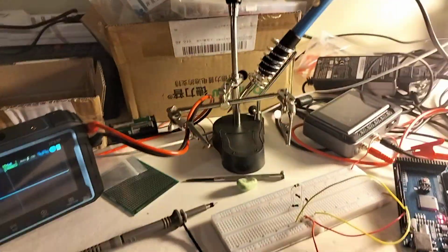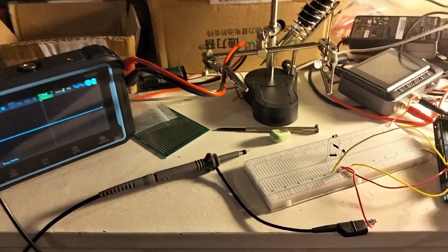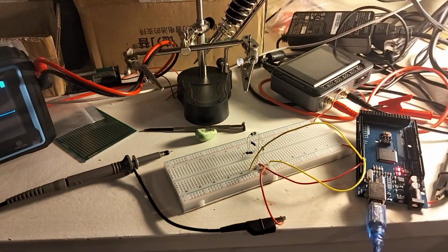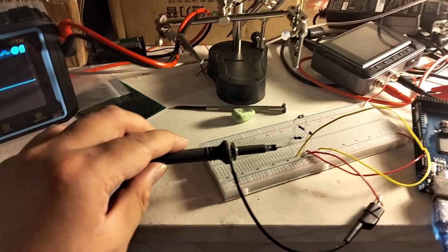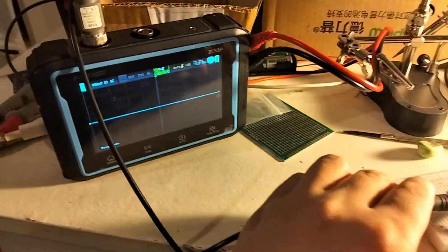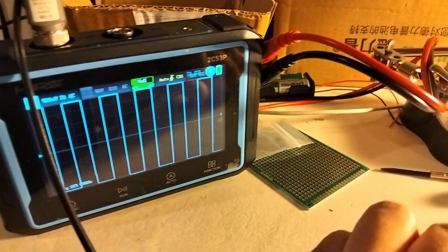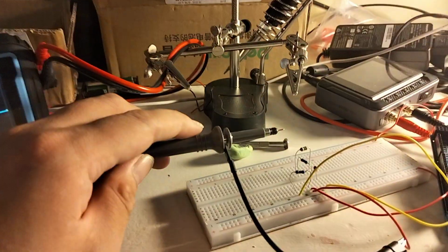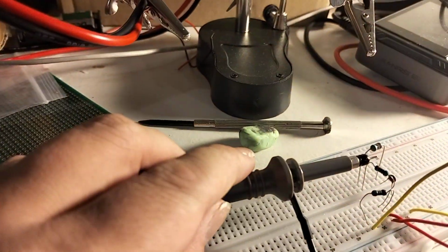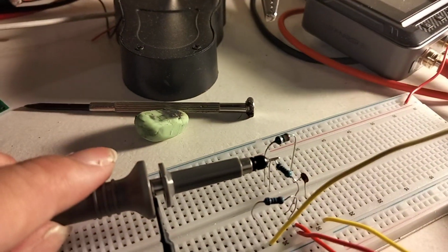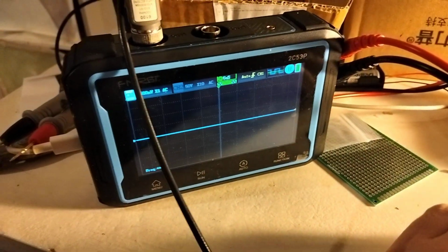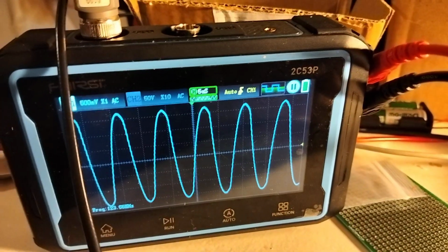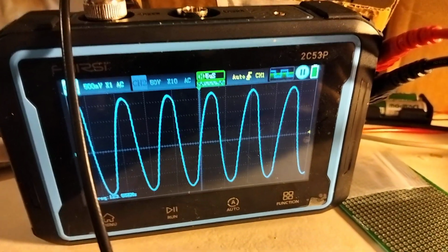Hi guys. This is a breadboarded example of a sine wave generated from the Arduino's PWM output pins. Over here, I have a standard PWM, as you can see in the oscilloscope. It's 123.5 kilohertz. And then with the filter, which I'll explain later, on this side of the circuit, I can measure a sine wave, or very close to a sine wave, on the same frequency, 123.5 kilohertz.